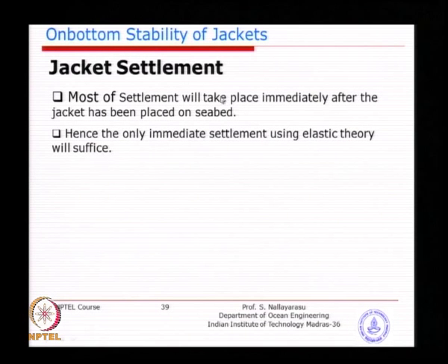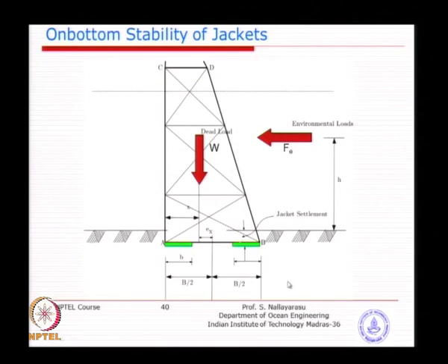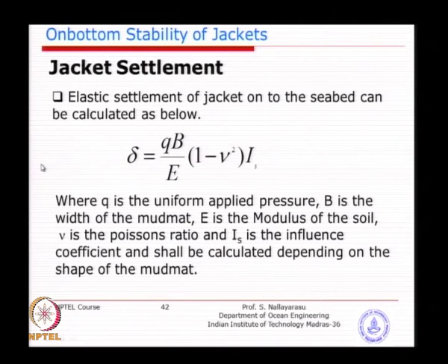Most of the time the settlement will be instantaneous, even if it is clayey type of soil, because once the settlement happens, you are going to do piling. You are not allowing consolidation settlement for several years, because already the jacket will be resting, or in fact supported, on the piles. So, what we are looking at is not the time bound settlement; the settlement happens instantaneously immediately after the placement of the jacket, which can easily be found by means of elastic formulas.